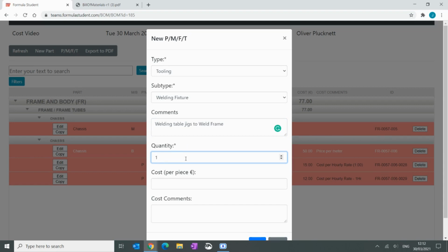If you're only making one vehicle, then it might be possible to use MDF to do this. You're only going to use it once. You could then cut the MDF out and get the chassis out. If you're making 100,000 of them, that's very much going to change. You don't want to be throwing away your jigs every time you manufacture one.